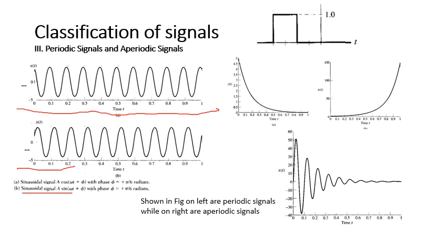Non-periodic signals are shown to the right of the figure. This is an example of an aperiodic signal. You understand it doesn't repeat. In fact, it's just a single pulse that exists from this time to this, and after that it is zero, and before that it was zero. Another aperiodic signal is this one, the exponentially decaying signal, right? That's also aperiodic. This one is another signal, an exponentially growing signal, so they are again aperiodic signals.